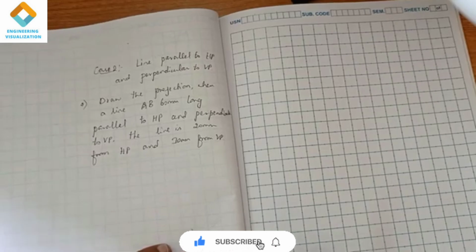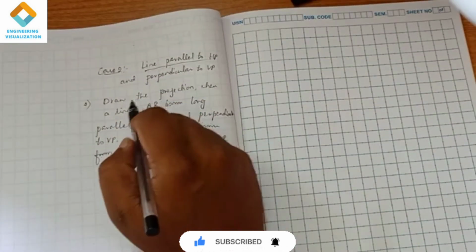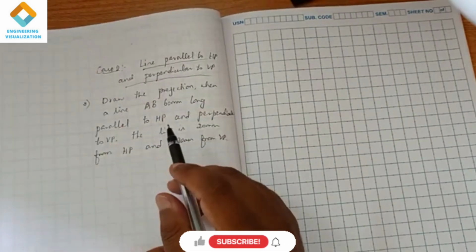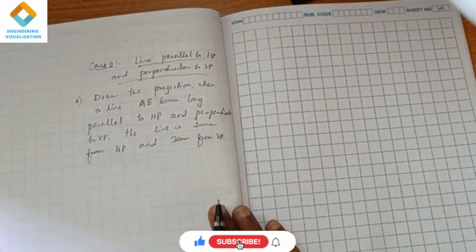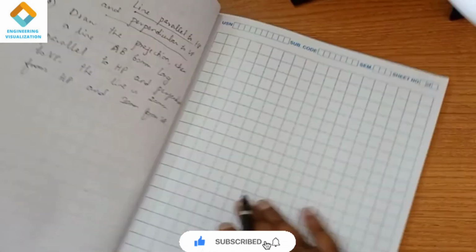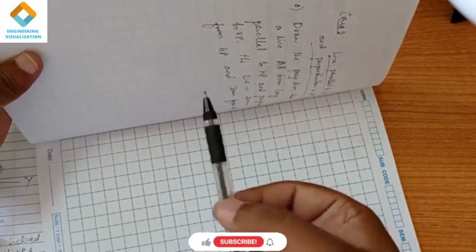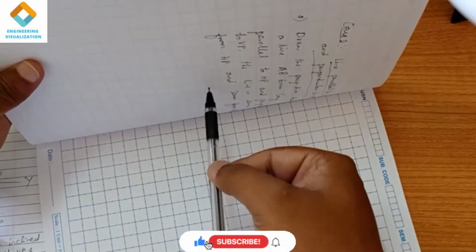Let us see the second case in projection of lines. The second condition is that the line is parallel to HP and perpendicular to VP. How to do that? Here you can see this is our vertical plane and this is the horizontal plane. In this condition we have to make the line parallel to HP. This pen is parallel to HP and perpendicular to VP.